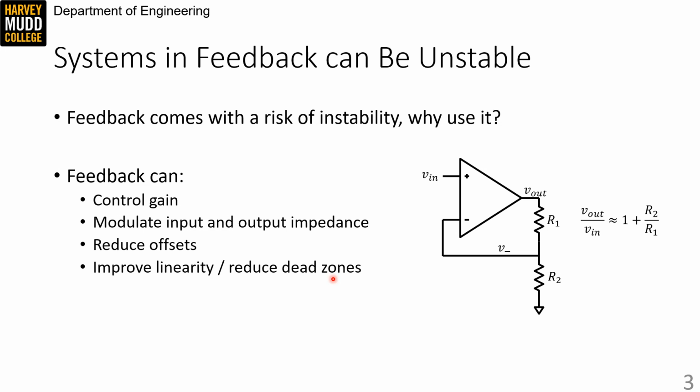So the op-amp is constrained to drive the inputs together. That's true even if the op-amp has a dead zone at the output. So the output will run past the boundaries of the dead zone in order to ensure that it has enough swing in order to force the input nodes to be equal to one another.